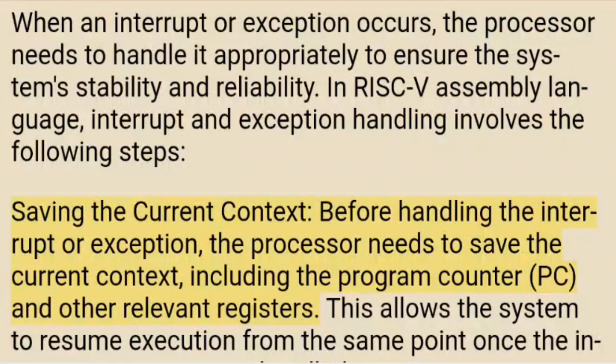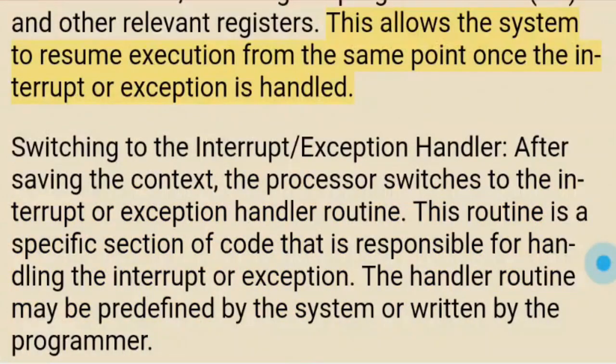Saving the current context. Before handling the interrupt or exception, the processor needs to save the current context, including the program counter PC and other relevant registers. This allows the system to resume execution from the same point once the interrupt or exception is handled.